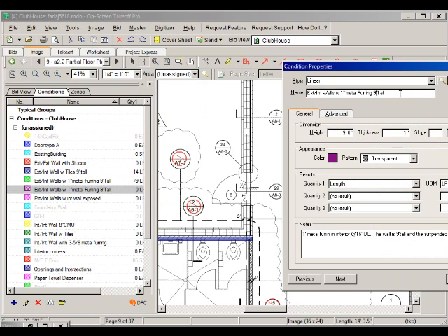This is going to be now 11 feet tall. So I'm going to change 9 to 11. 1 inch metal furring. This will be furring in interior at 16 inches on center. The wall is 11 feet tall. And the suspended ceiling here stops at 8 feet 6 inches.